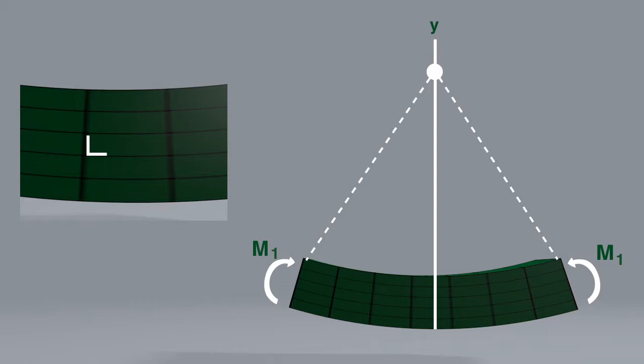Some beams are not in pure bending. In fact, most beams are subjected to loads that produce both bending moments and shear forces, which is called non-uniform bending. In these cases, both normal and shear stresses are developed in the beam. Normal stresses are calculated using the flexural stress formula. We will now take a look at the distribution of shear stresses associated with the shear force in non-uniform bending.